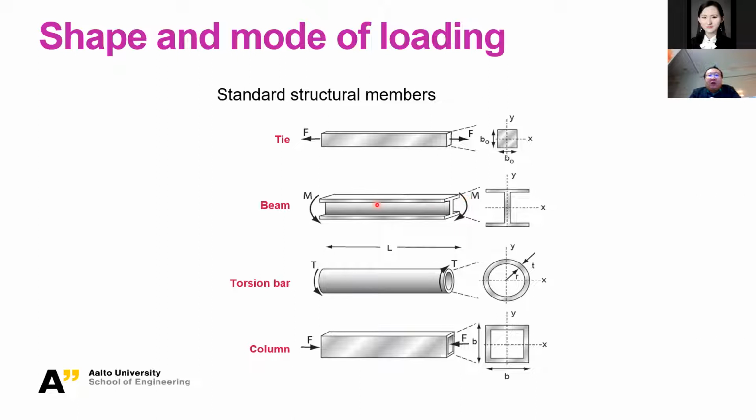We're not changing the entire shape. You can see the assumption is basically a uniform extrusion of the cross section. So we don't allow any tailoring at different positions in the longitudinal direction, which is just to make it easier to understand the concept and to do the design.